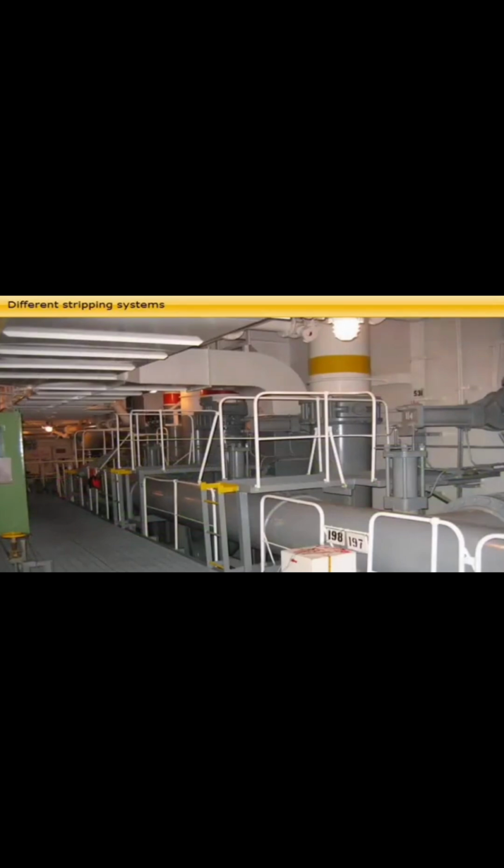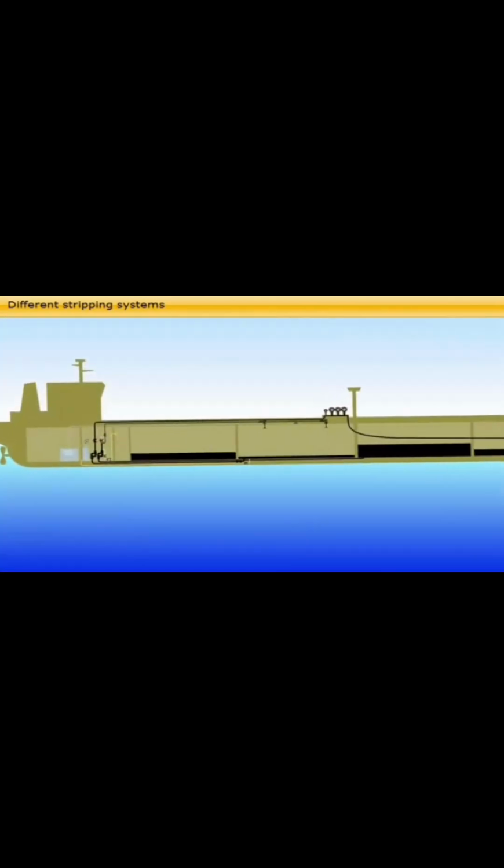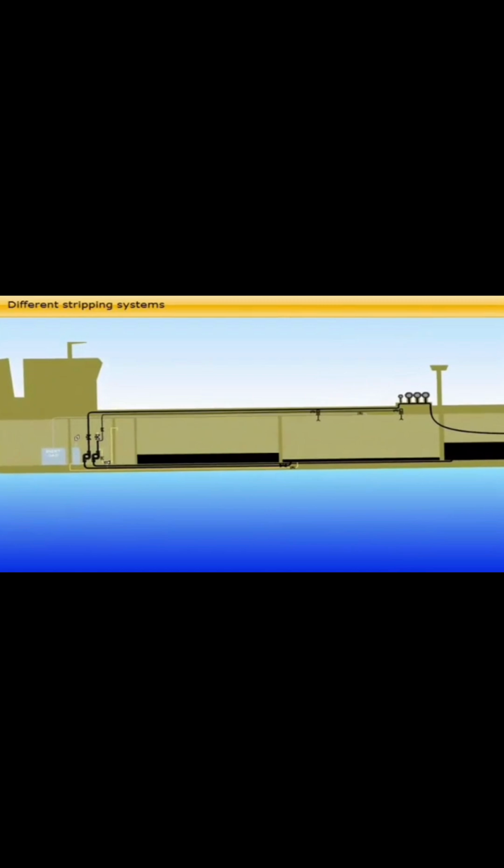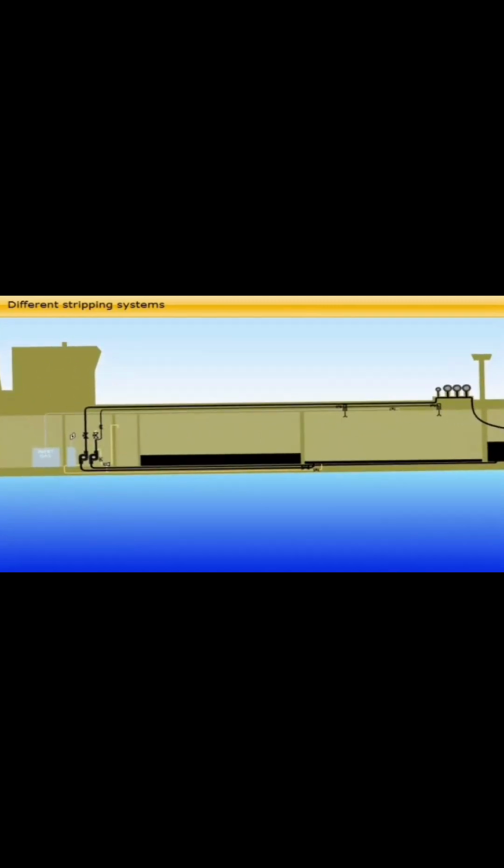The final draining of the vessel's cargo pumps and lines in the pump room and on deck shall be carried out by means of a stripping pump, normally a steam-driven pump, which can deliver the remaining oil to shore through a small diameter line, also called a Marpol line. This line is connected to one of the manifold lines and outside of the manifold gate valve in order to enable direct discharge to shore after the manifold valves have been closed.